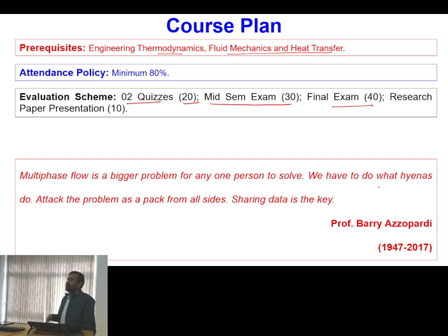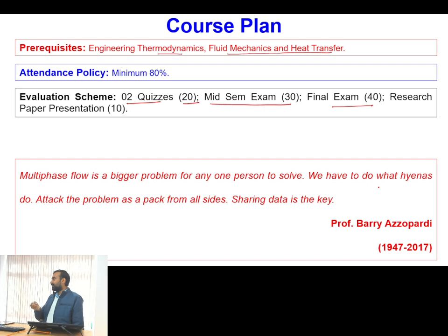We have some governing equations, for example, the continuity equation and momentum equation. We simplify these equations for the given flow situation, and once we have the simplified version, these equations are subjected to the set of boundary conditions applicable for the given problem, and then analytically we try to find the solution.